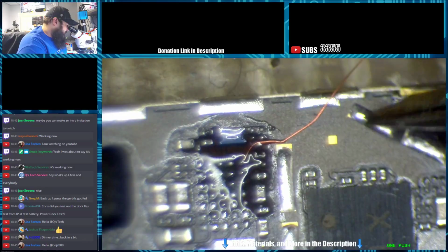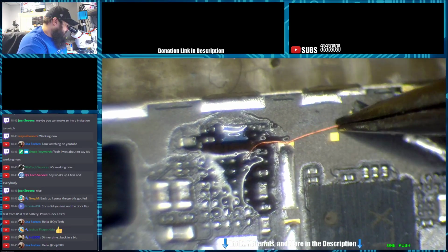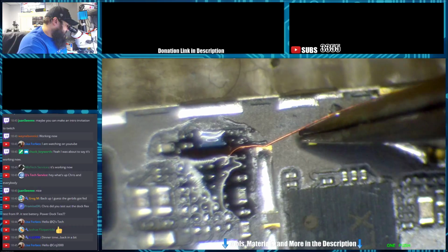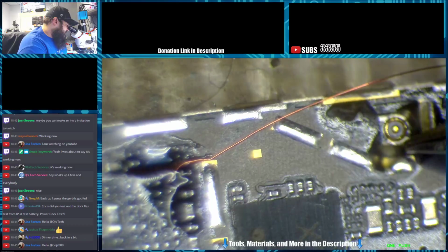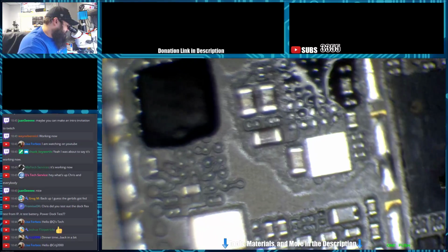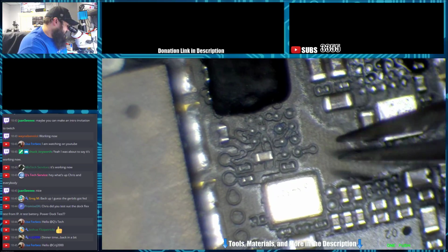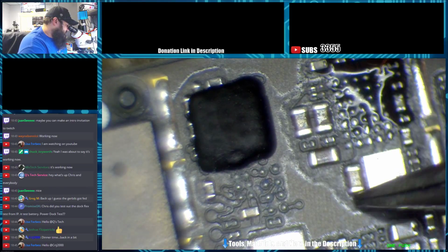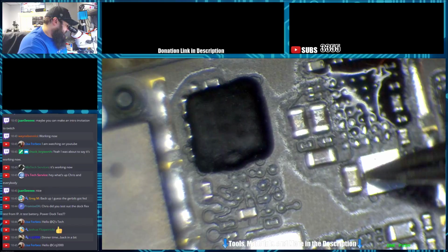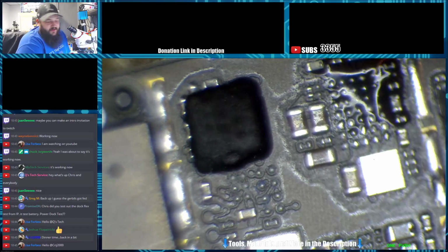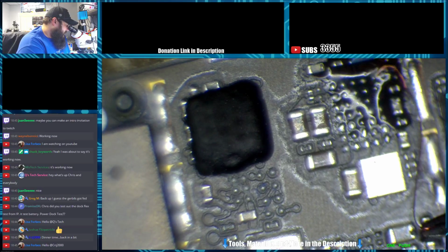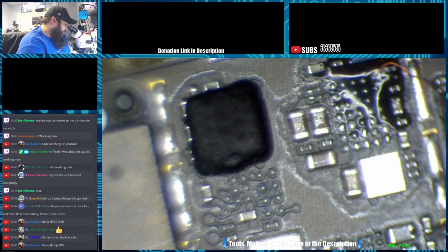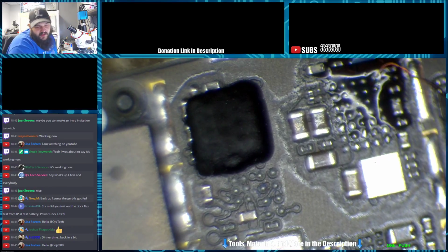So we're going to need ground for one side of the resistor. So what I'm planning on doing is attaching a resistor to a ground plane somewhere. I don't know if I want to do it here though, because the shield runs here on all these points too. Since this resistor or this capacitor up here, one of these will be VCC main, which we'll need also, I may just come around here and catch the ground and power directly off of one cap, and that way we kind of cut down a little bit on what we have to do.